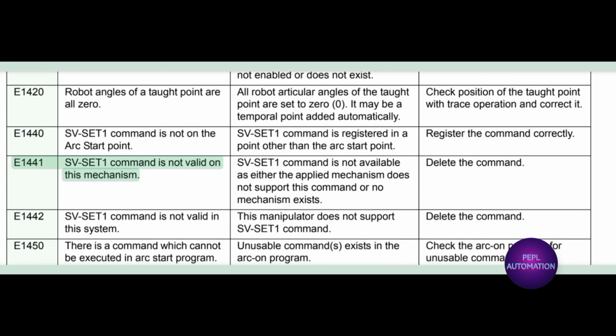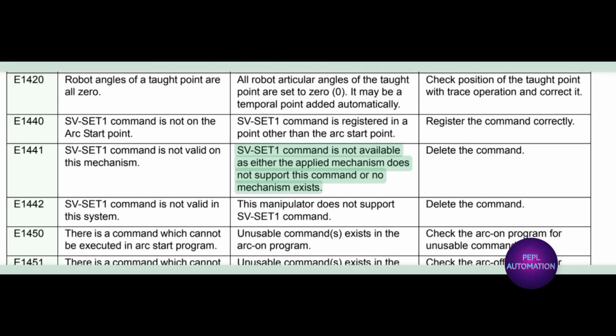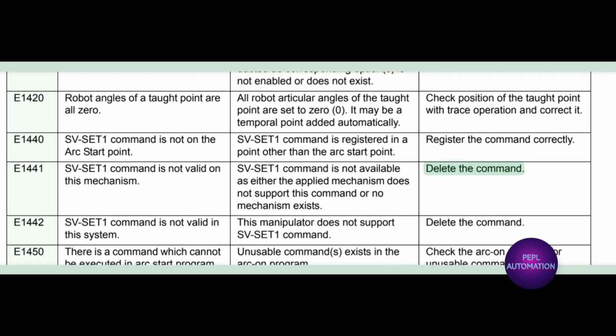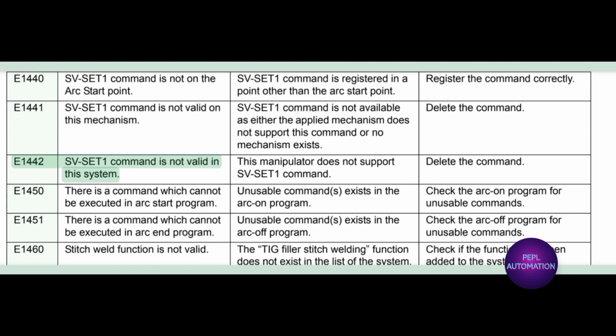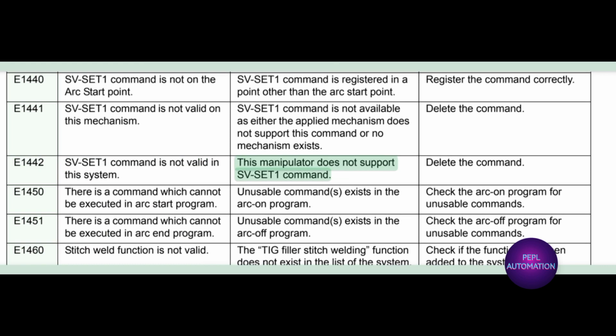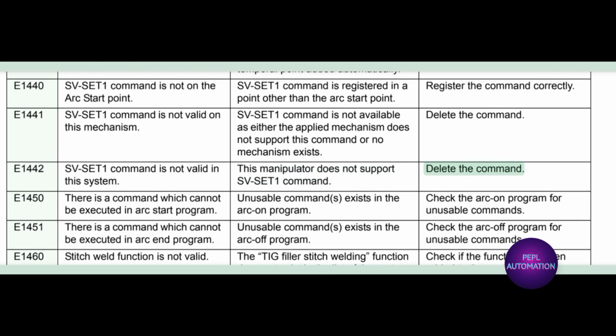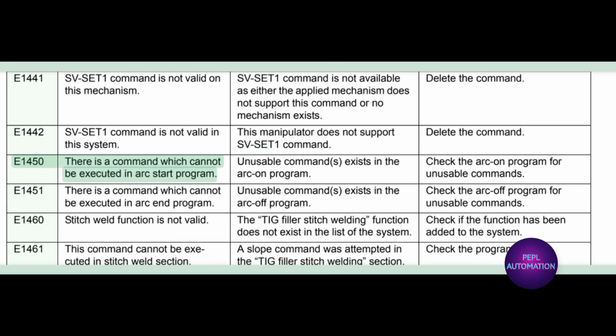E1441 SVSET1 command is not valid on this mechanism. SVSET1 command is not available as either the applied mechanism does not support this command or no mechanism exists. Delete the command. E1442 SVSET1 command is not valid in this system. This manipulator does not support SVSET1 command. Delete the command.